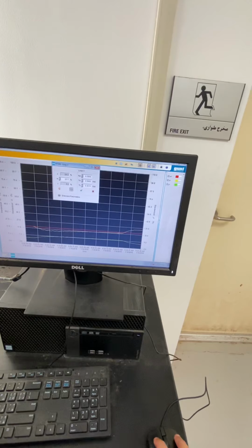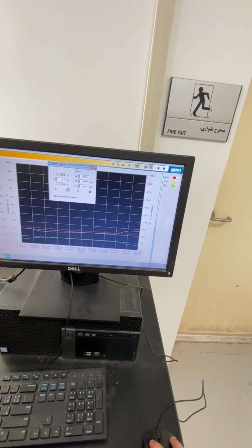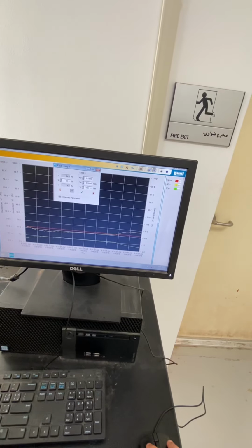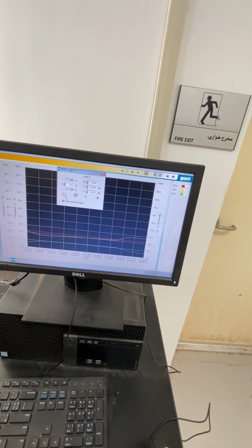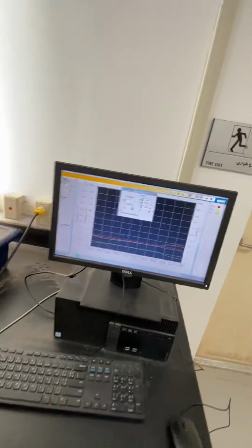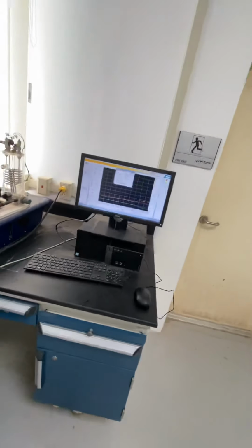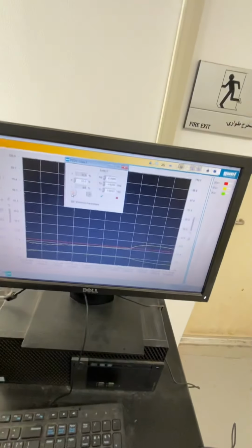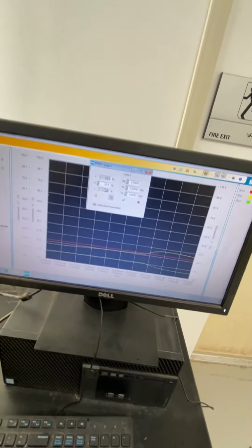You can see right now the process value is almost 20% at a higher output signal. Okay. So yeah, it's actually a very difficult problem to detect, but that is one of the ways to tell whether you have a problem in the process, which is most likely a stuck open safety relief valve.